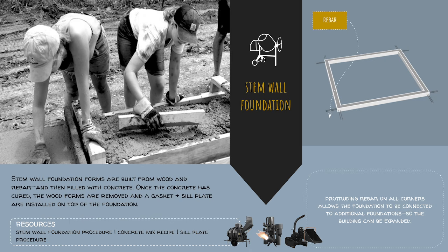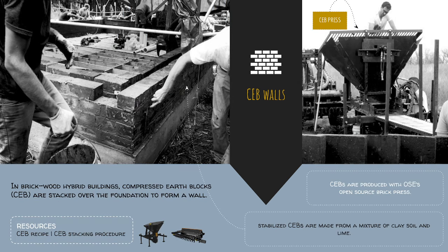This is a way to do a pretty low cost, low embodied energy foundation, because there's a little bit of concrete on the edge, but most of it is just gravel. So it's 10 times less embodied energy for gravel compared to concrete. Now gravel isn't free, because there's a lot of energy that goes into actually breaking up that rock and transporting it in trucks to your site and all that. There's energy involved in that.